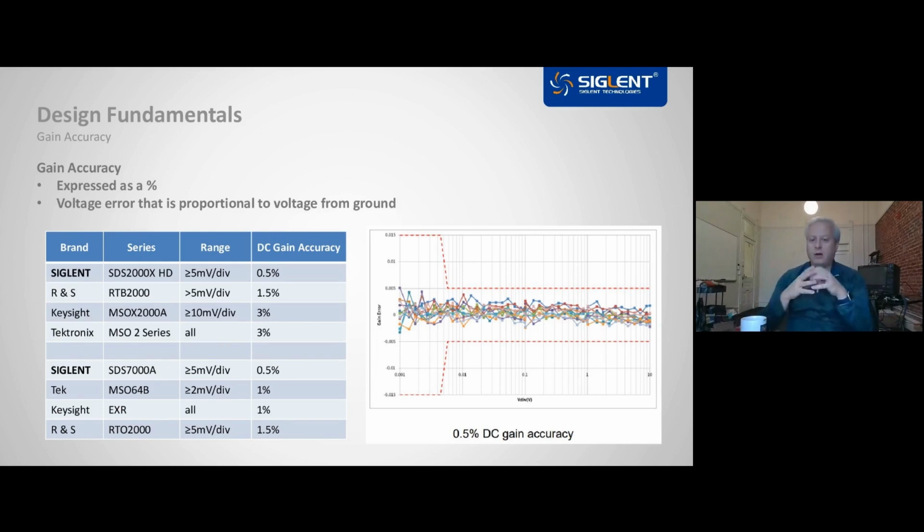First, we'll see later how scale offset capabilities on a range can empower additional measurement capabilities. Improved gain error is often a necessity before extending those offset scales. But since these values are typically 3% or less of a signal, as we see on the chart here, and tend to operate more as an offset than noise, they would typically not be as important in visual applications. For instance, many scope applications are focused on changes and signal artifacts in time more than whether the line on the display is 3 millivolts too high or 3 millivolts too low.